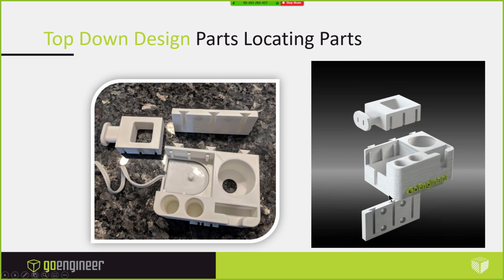In this exploded view, you can kind of see that. You can see how they're going to drop in. I have this dovetail here that's going to drop down into that slot, and then these little channels are going to align with the little cutouts here. I designed this little Sonicare toothbrush holder to replace a shelf. The Sonicare kept falling off the shelf, and so I also wanted to create a top-down design, and apply a lot of these things that come with this topic of design for manufacturing.